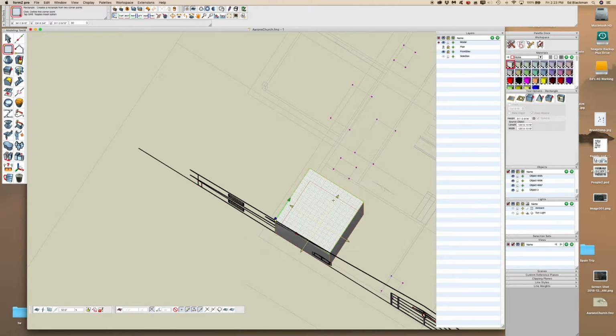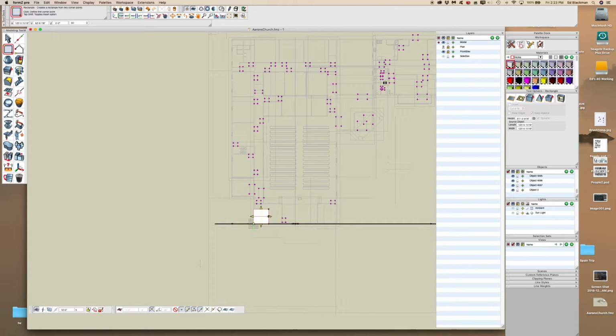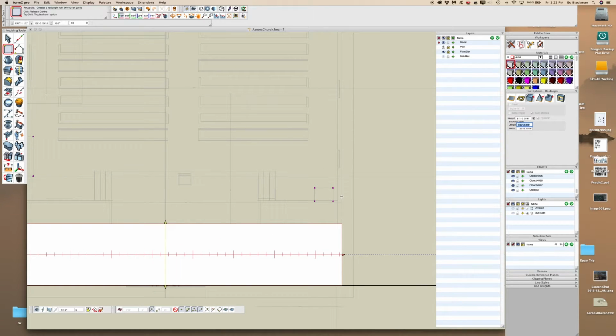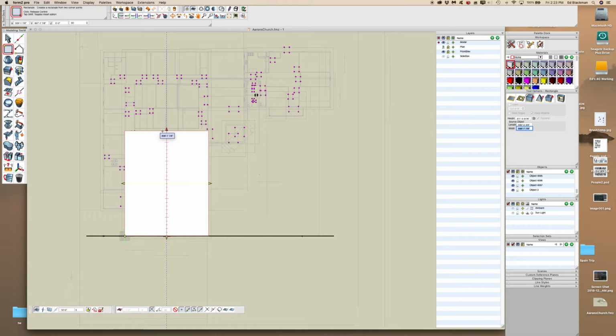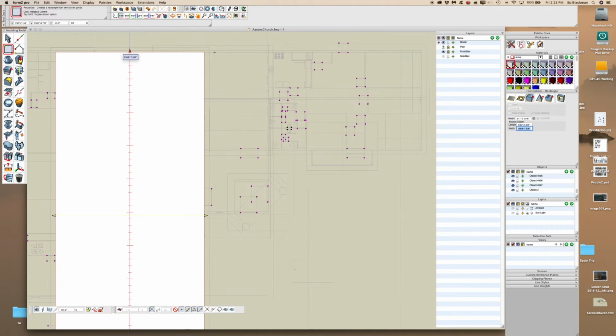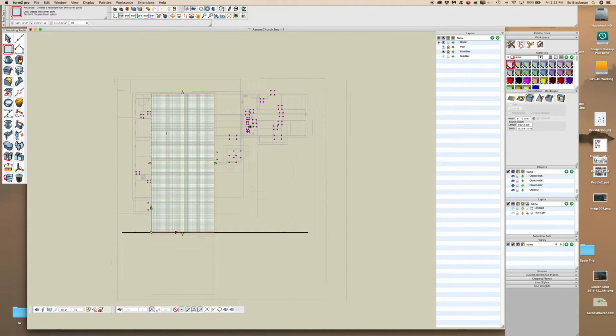We'll just click. And now these arrows allow you to modify the shape after you've drawn it. So I'm going to simply go here and grab this arrow and go over, and I'm going to zoom in. You can do all these things at the same time. I'm going to zoom in until that is right at that corner, and I'm going to click. Then I'm going to grab this one, and I zoomed out. I did it with my fingertip. And I'm going to go all the way to the back of the church here on this wall and click. And that's good for that.